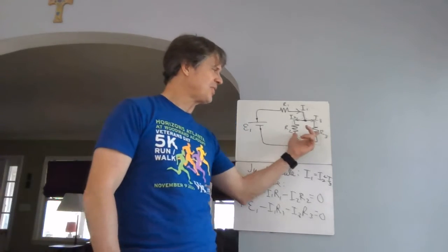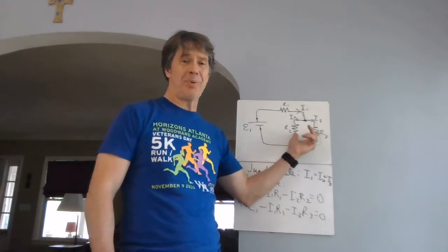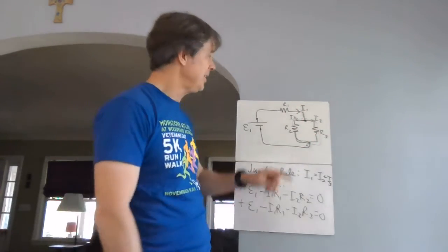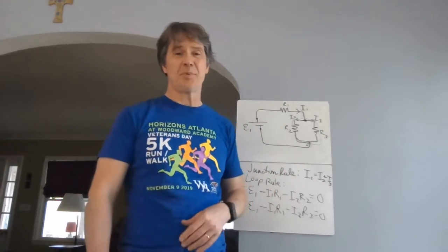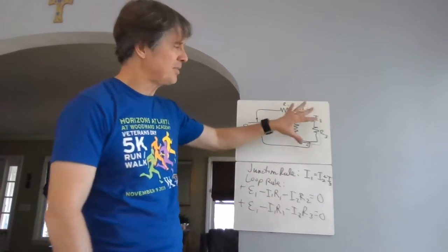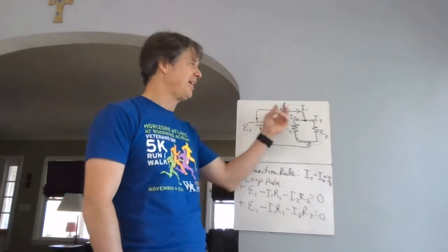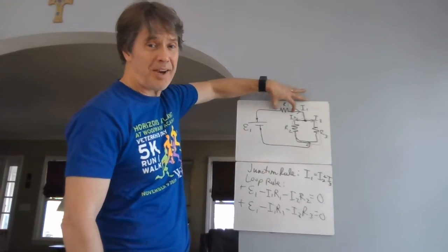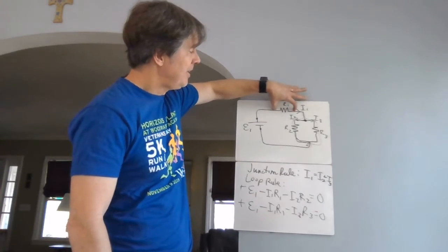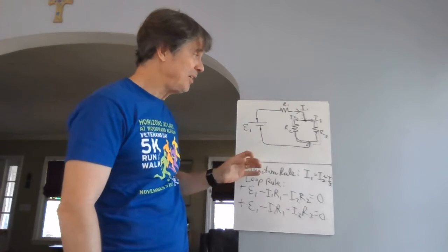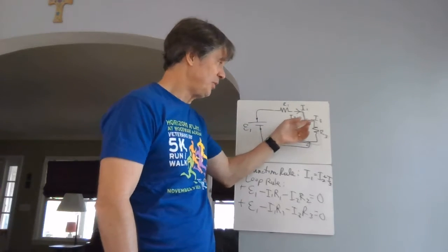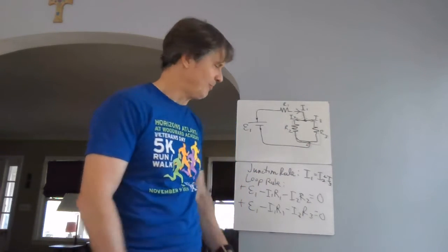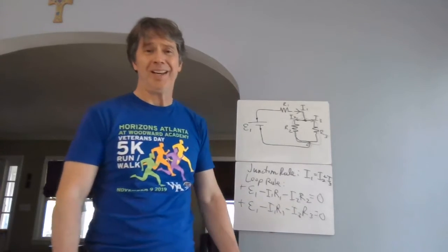It's easy. I just take these 2 here, say they're in parallel, do the little 1 over rule to get the effective resistance of that. Then I add in that one because it's in series with them. And that's like some big black box, big mushed together resistor out here. It helps me find I1. Once I know I1, I'll find the voltage drop from V equals IR across this. And with that part of the voltage drop accounted for, I would know the voltage drop across here and quickly find these currents. There's multiple ways to do it. Why bother? You wouldn't have to.